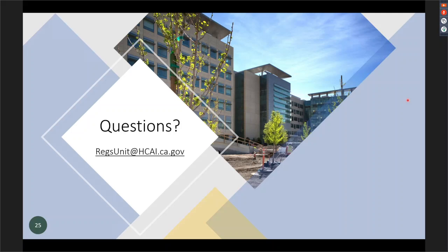It doesn't change anything in your design, but there might have been something missing on the drawings, a note, a dimension, a shading, something that was missing that was just to make it clear. You answer the question, you don't have to change the drawing. You may add a note to the drawing just to repeat what the question was for the RFI and annotate it that way. That's what we're talking about when there's no change to the design.